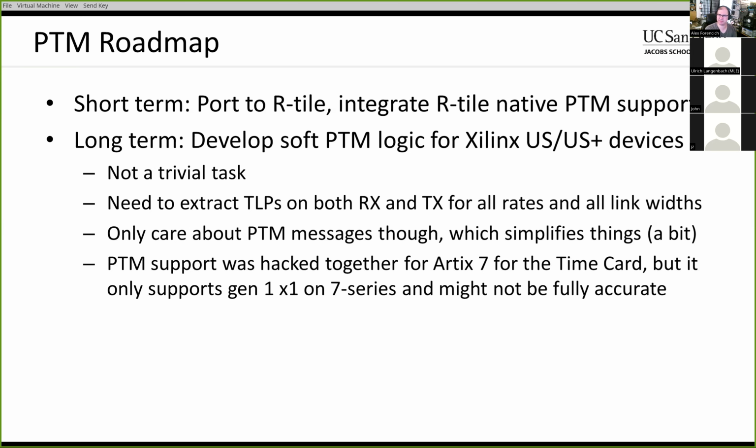Now, I know there was an effort to put together PTM support for Artix 7 on the time card, but it only supports like a Gen 1 by 1, as far as I'm aware, and it also might be subject to queuing delays within the hard IP core. Not 100% sure about that. That'll definitely be one of the things that I'm looking at for implementing PTM properly, is to make sure that we're timestamping stuff on the serial side to make sure that it's going to be accurate even under load.